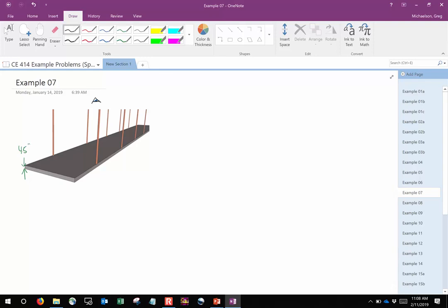Okay. So looking down on the walkway, what we've got is a walkway that, for the sake of discussion, we'll assume goes on forever. And if we're looking at it from above, what we would see are these rods sticking out like that. So those are the rods supporting the walkway. Okay? And so let's pick a random rod and draw out its tributary area, right? Remember, how do we define that? We define it as halfway over to the next adjacent rod, right?